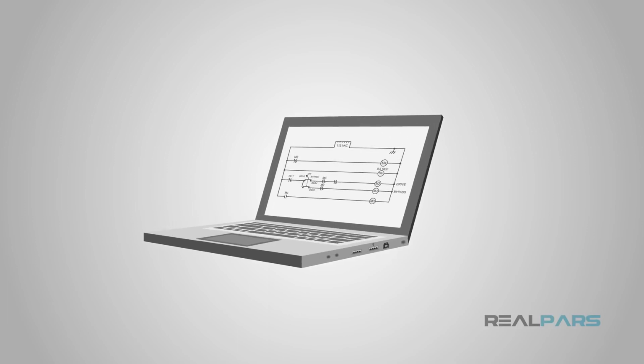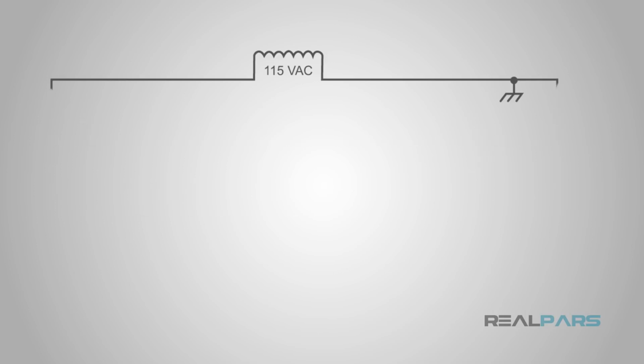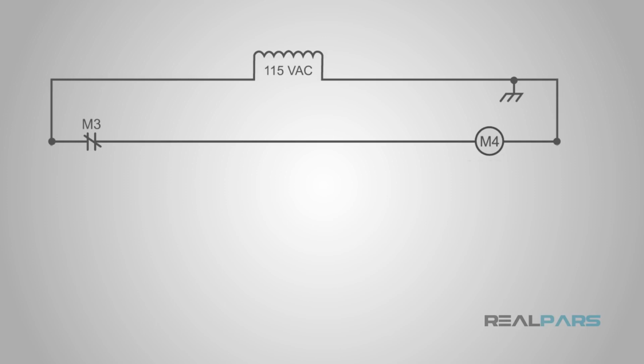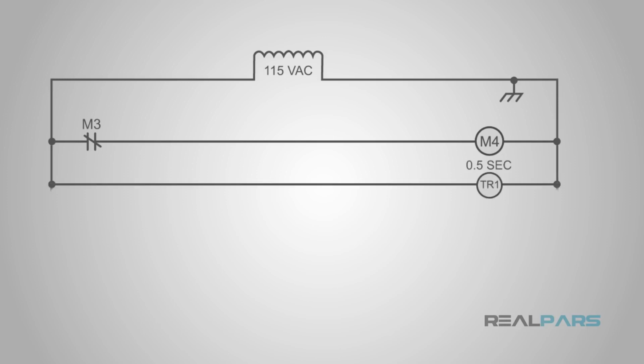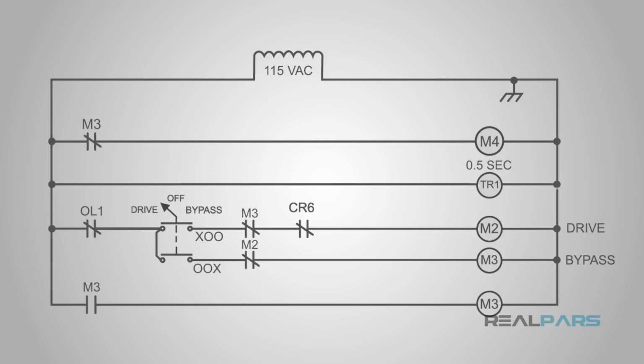In order to understand why we call it ladder logic, you need to look at how we document relay logic controls. The actual ladder was the drawing of the control logic, an illustration of how the relays were wired together. Even today, a lot of the conventions that led to the ladders are still in use, and I'll use a recent example drawing to illustrate this. Here is a simplified drawing of a control circuit. The appearance is what led to being called ladder logic, since it superficially resembles a ladder.